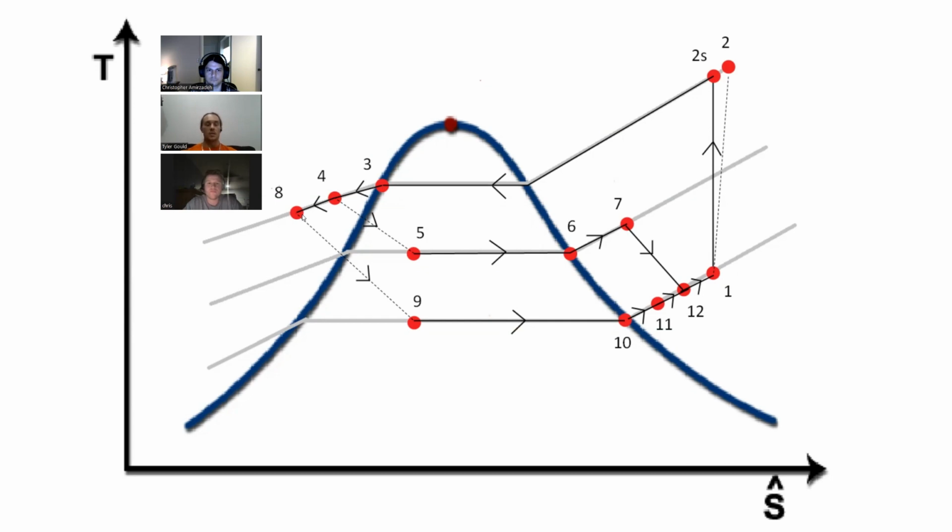That's where our flow is diverging to the two separate pressures, and it's dropping down to state 5 and 9 on the two different isobars, and then across this to the saturation line where it exits each evaporator as a saturated liquid, as Christian said. And then those go down, and you can see at state 12 is where both of the flows meet back together again, and it becomes a whole single mass flow back into state 1, which is where it gets pumped back into the compressor.